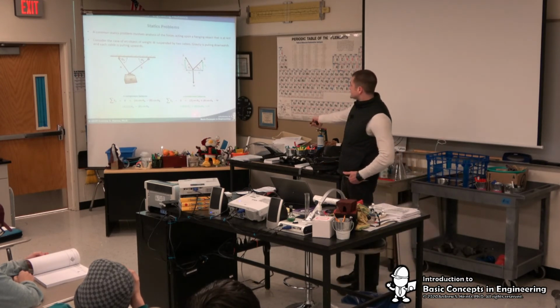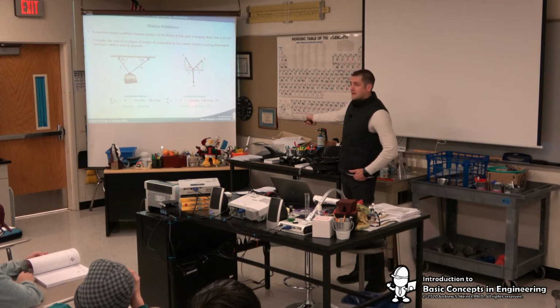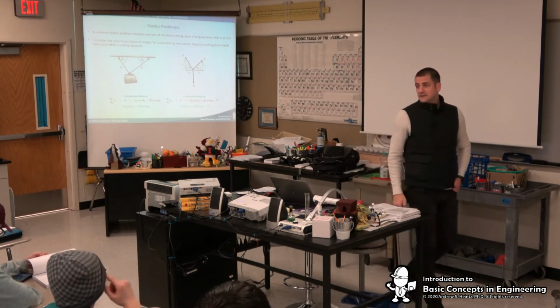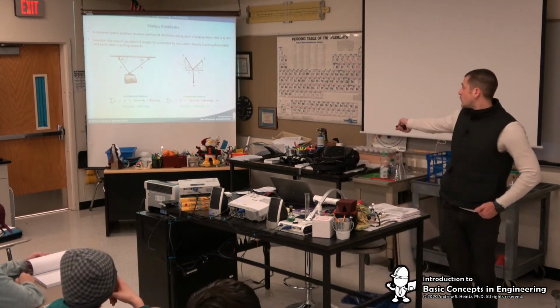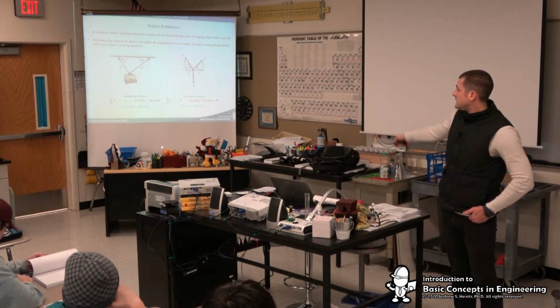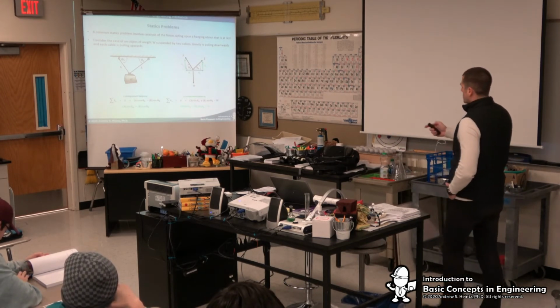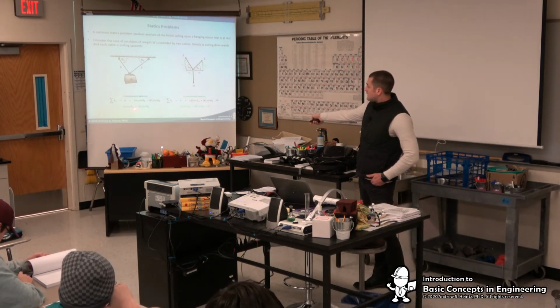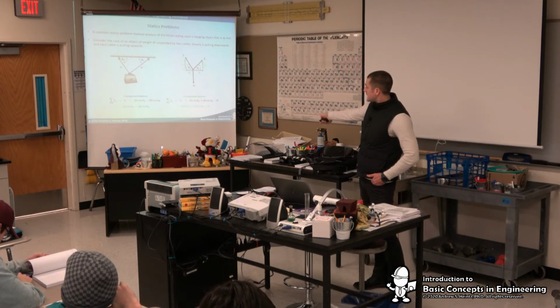And then in this case, the y component balance, we have the sine of theta a, sine of theta b, but we also now have to subtract the weight. So we bring the weight to the other side and we get sine a, sine b equals w. But remember, we're multiplying here by variables. We have a cosine theta b, cosine theta a, sine theta b, sine theta.